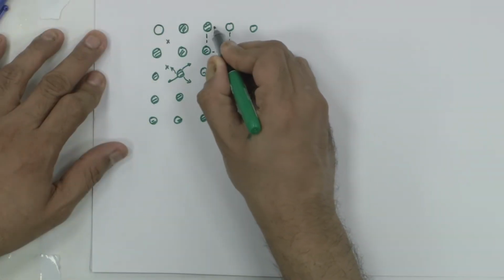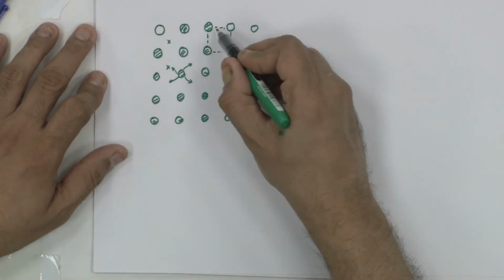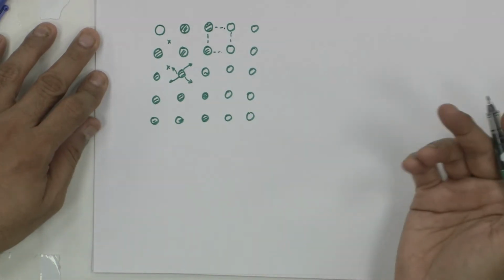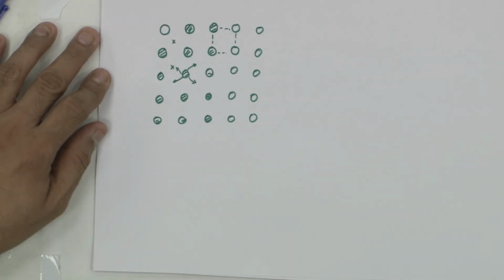Why? Because you use the concept of hydraulic diameter and try to convert each of these flow paths into an equivalent circular pipe geometry with the heat being distributed around the periphery, and you use the results that you obtain for circular pipe geometry very easily for even a complex geometry like a rod bundle. Of course, what you predict using circular pipe geometry is not going to be what happens here. There are several aspects like cross flow happening between these two paths, cross flow this way, turbulent mixing, etc. So, there are correction factors which would be used.